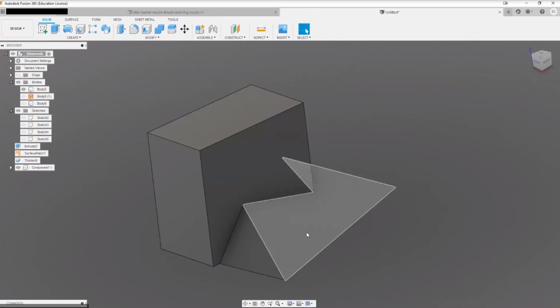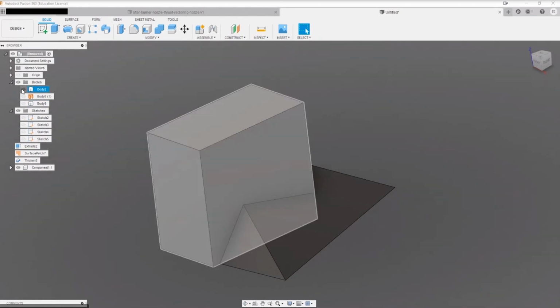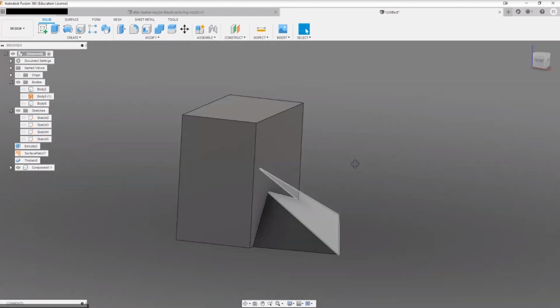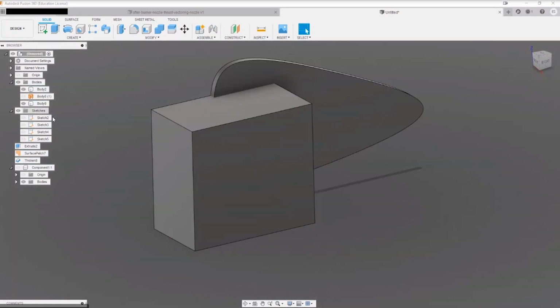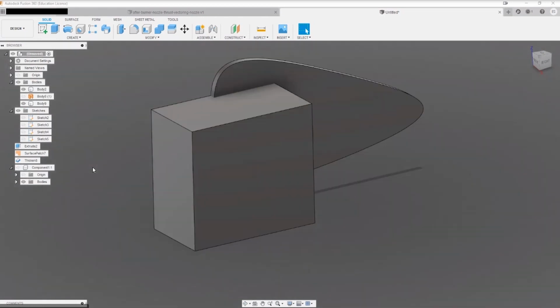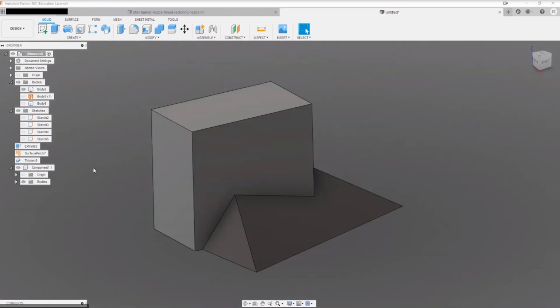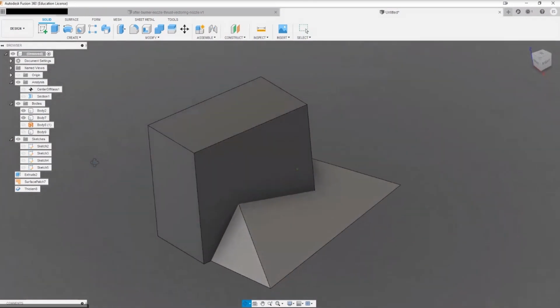So we no longer have the two individual components. We just have this entire single block, right? It's already created a new component for us. So if we remove that, that's it. So we've got the component. I'm going to hit Control Z on that, and we're going to go back. Oh yeah, by the way, if you captured the design history and you wanted to undo something, this would take ages. It would recompute, and chances are it might even crash. So again, this is another point for turning off the design history capture.